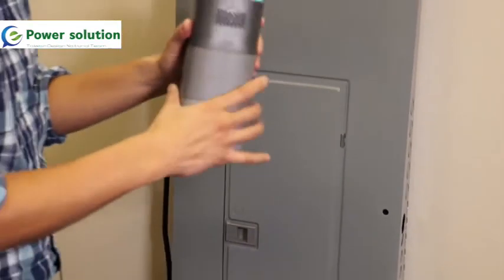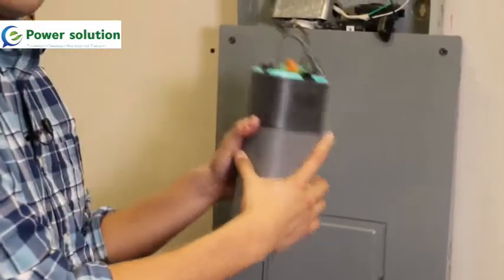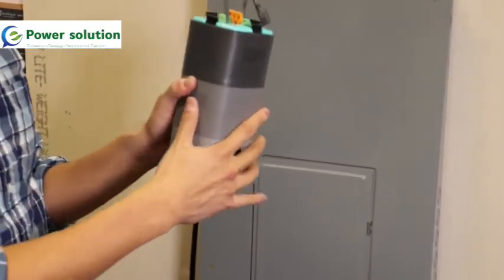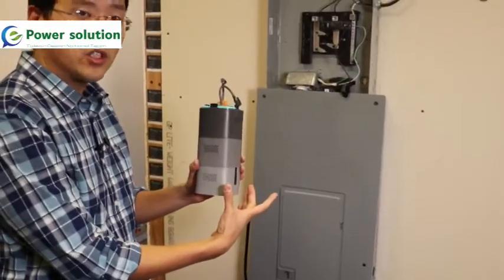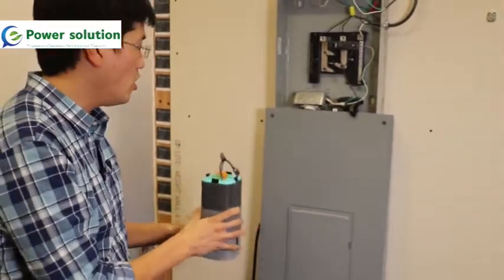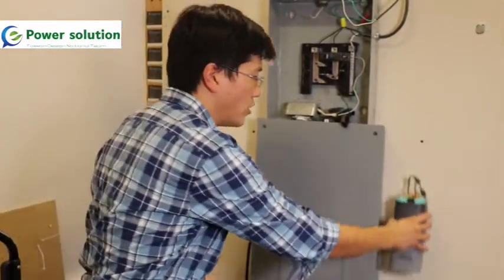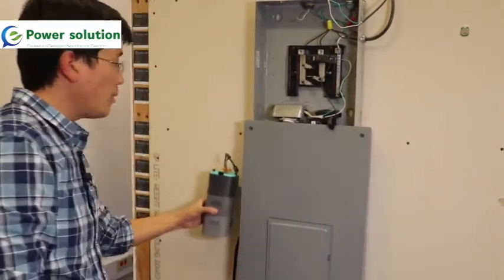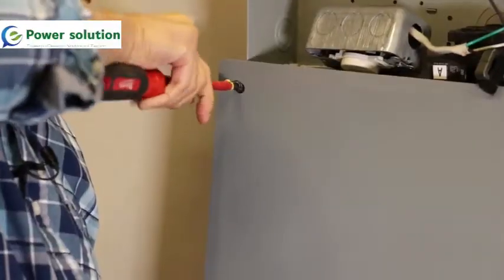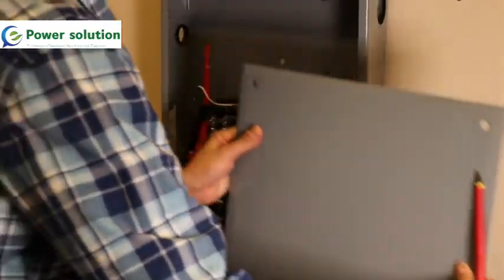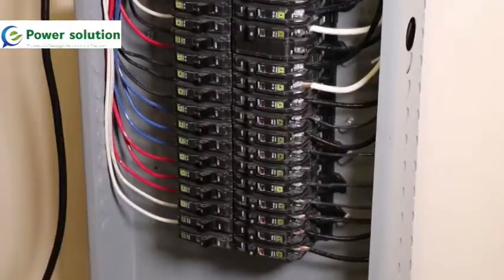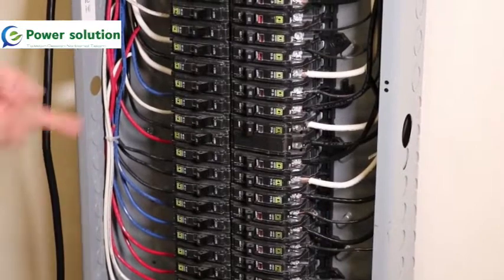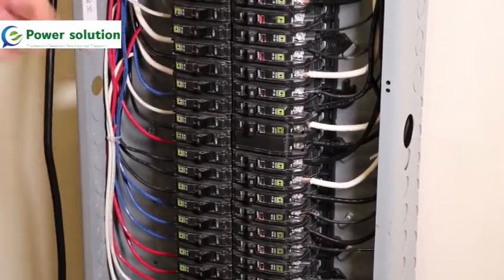When installing on the panel, we select where we want the transmitter to be attached to. Make sure you have clearance of 5.5 inches by 5.5 inches deep by 15.5 inches tall, wherever along the side you're installing the panel. If there's an obstruction on the panel that prevents you from having that distance, you may place the transmitter on the opposite side. When your panel's open, some panels will vary in color. Ours have red, black, and blue primarily. They will alternate in color to indicate different phases.